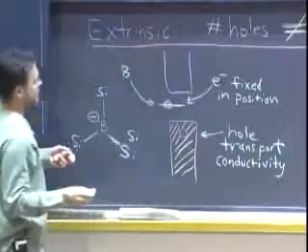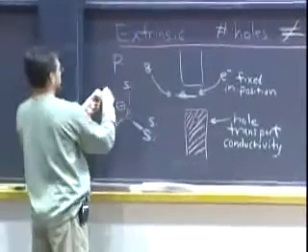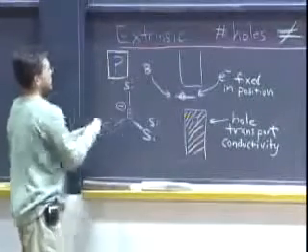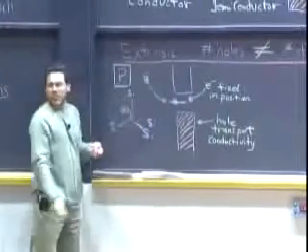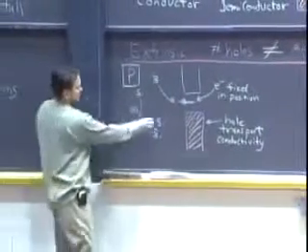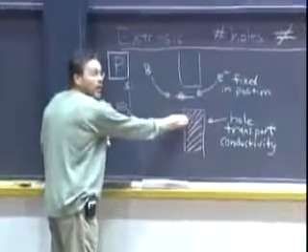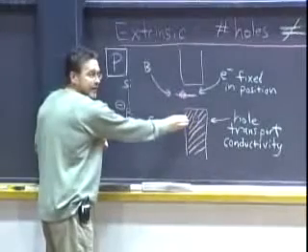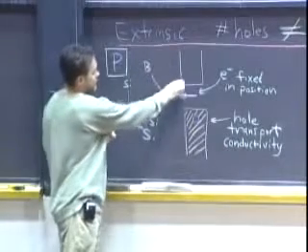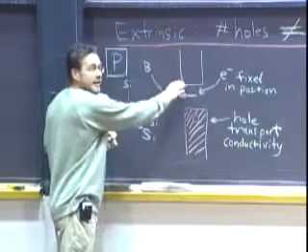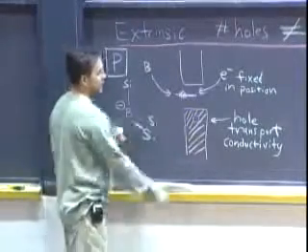And so notice that in this type of semiconductor, and this, by the way, is a p-type semiconductor. P for positive. You're putting in a hole on that boron. So this is a p-type of semiconductor. This thing is stuck on the boron, and it generates a hole that is free to move in the valence band and giving rise to conductivity. So in this extrinsic type of semiconductor, you're not necessarily getting any conductivity up here in the normal conduction band, but down in the valence band due to the creation of the hole.